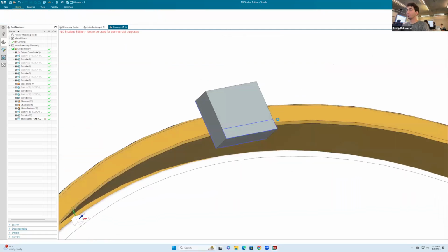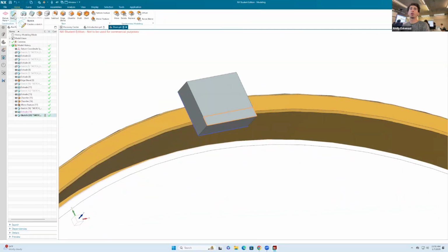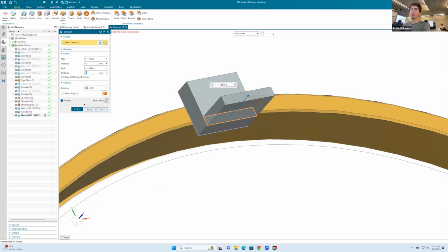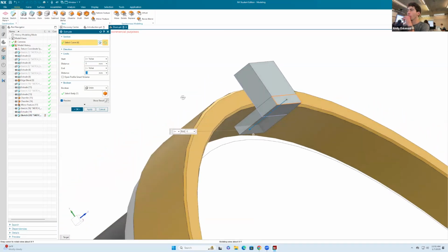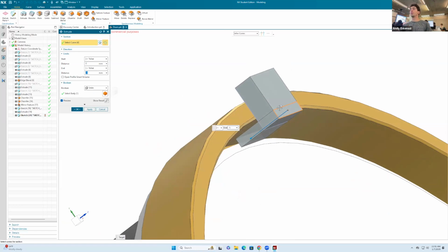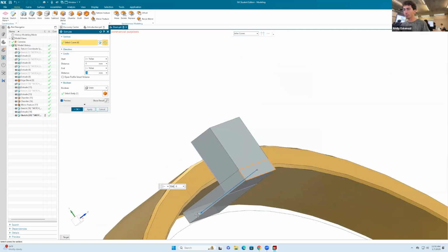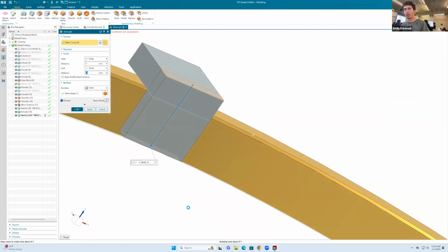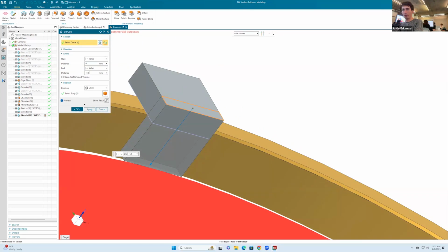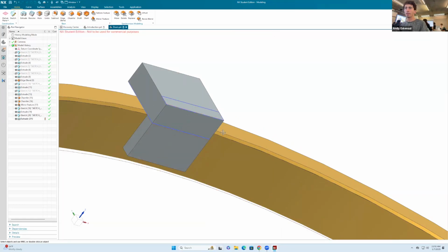And I'll say finish. So then we go here to extrude, and we're gonna extrude downwards by -5. So then it goes like that. So this is the feature. We'll go over some of these things on later sessions, but this is a unite, which means even though they're intersecting, it becomes the same piece. And I click, actually, maybe I'll do -6. So it goes almost right, -5.5. There we go. I'll say, okay.